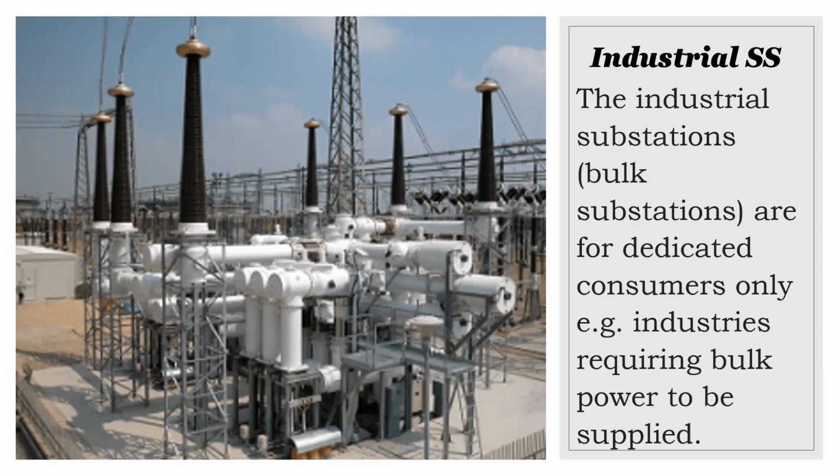Everybody cool with that? Now, the reactive power demand would be coming from the use of motors and that sort of thing. Agree, Ms. Michael? Yes, sir. All right. Now, if I'm putting in a lot of motorized loads in my home, or should I say my facility, then the utility company will have to make the necessary provisions to supply that, which means that the transformers, which are rated in volt-amperes, would have to be of the right capacity to supply.